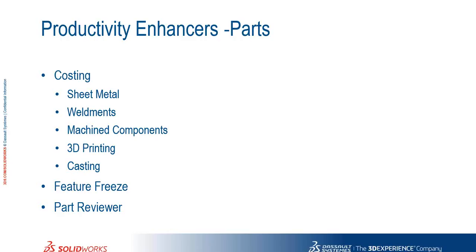One more new enhancement which has been added is an option of feature freeze. So what feature freeze does is like if you're working on configurations of a single part, right, and you make some modifications and you want to see how that modification is applied to the rest of the configurations. If you change the configuration, you know that there's always some kind of a rebuild. It takes some time for the rebuild option, right? Now, even if the time taken is hardly 10 or 15 seconds, it's quite frustrating at times. So this is where feature freeze helps you out. What you're going to do is freeze all the features so that the time taken in between changing the configurations is minimum.